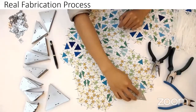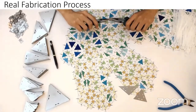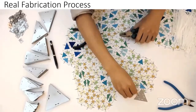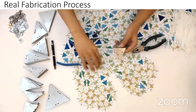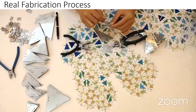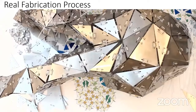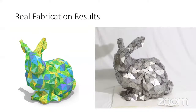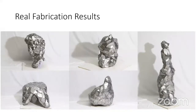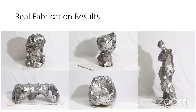For real fabrication, we first select the templates based on the instruction, then bend the stainless steel hinges to match the target angle, and fix the triangle plate and hinge using nylon cable ties. The assembly process for two nearby triangles is straightforward, and this process is used to manufacture the entire model. This is the fabrication result of the Barney model. Here are more fabrication results by ourselves. All of the models are made based on the same 9 triangle templates.